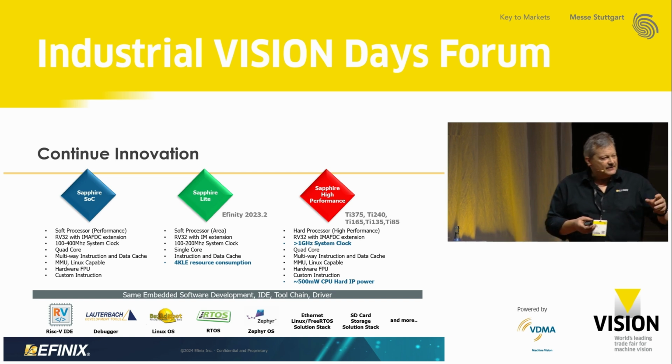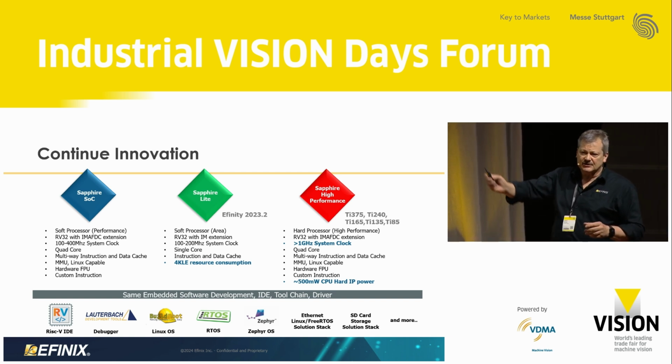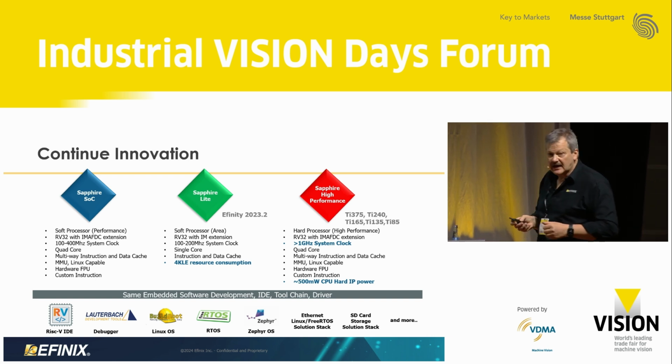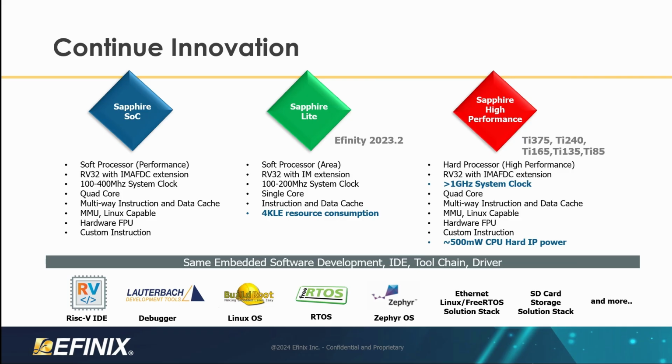If you say, RISC-V is nice, but I do not need such a big system, we are supporting a Sapphire Lite as well. Just if you need a controller which is putting some register here, some information there, then we are offering you a 4K logic element soft processor, RISC-V based. And then our high-end, the Sapphire high performance SoC.